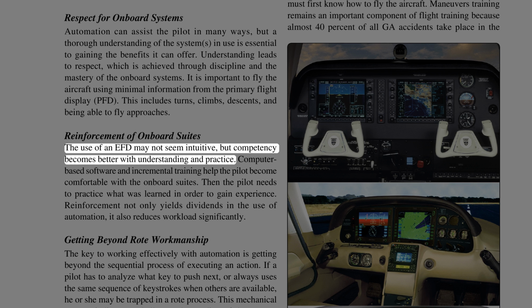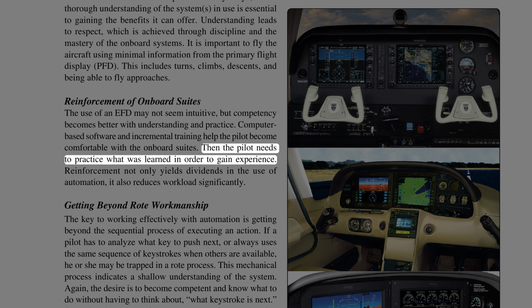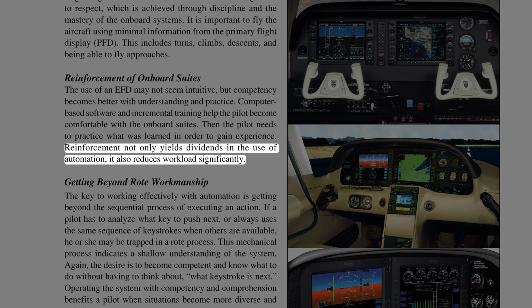The use of an EFD may not seem intuitive, but competency becomes better with understanding and practice. Computer-based software and incremental training help the pilot become comfortable with the onboard suites. Then the pilot needs to practice what was learned in order to gain experience. Reinforcement not only yields dividends in the use of automation, it also reduces workload significantly.